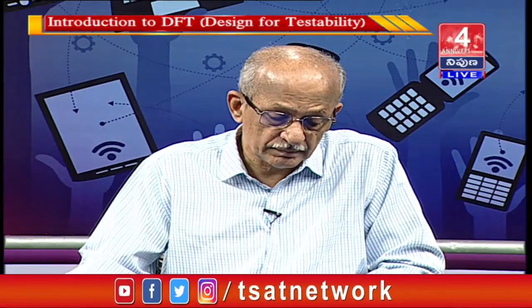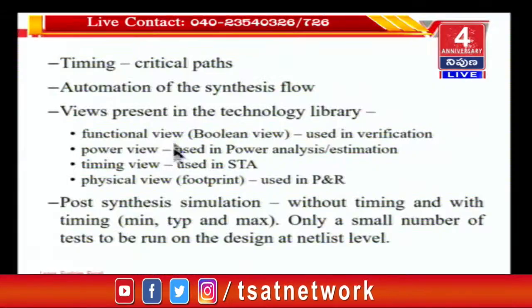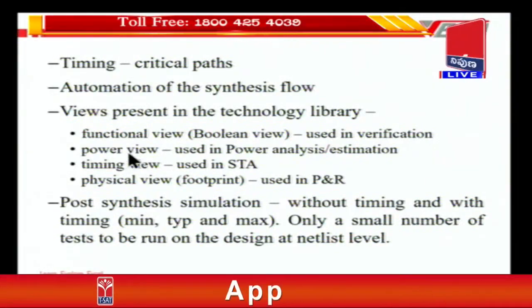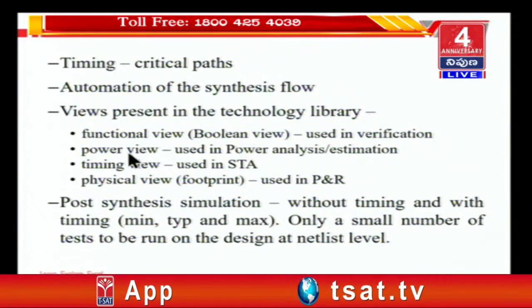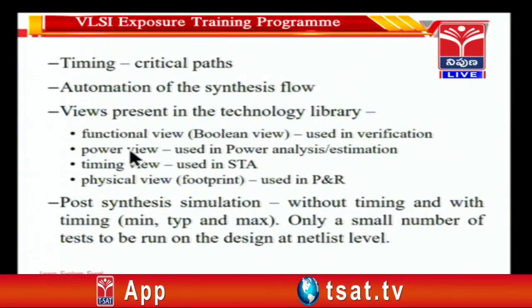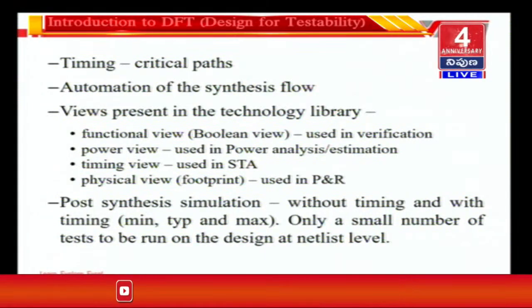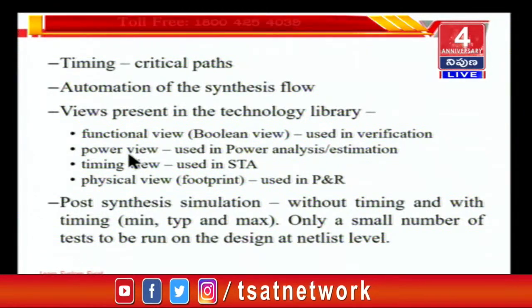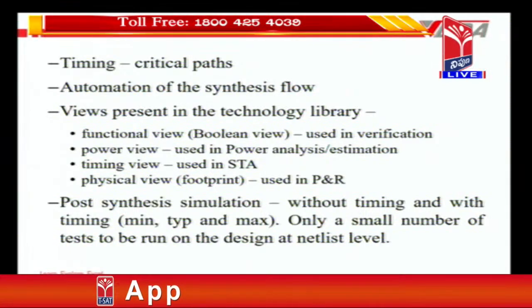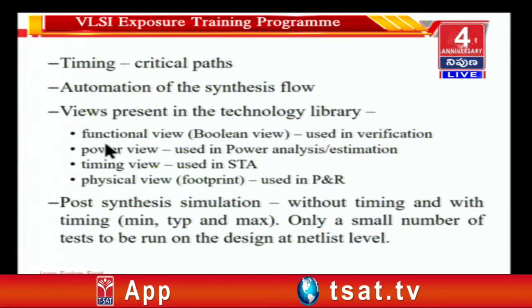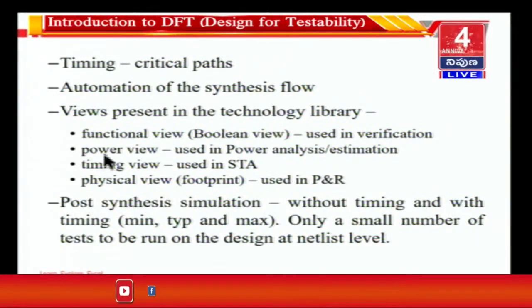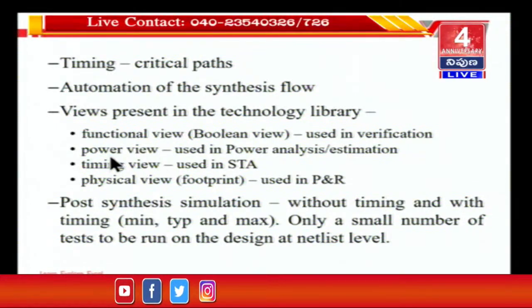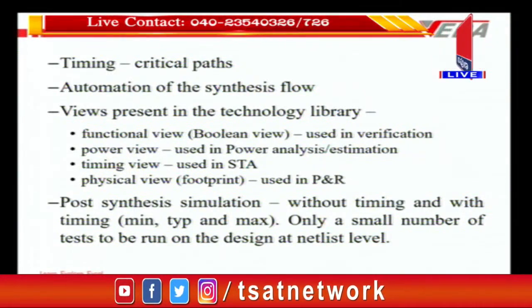As we have mentioned earlier, the power of logic elements in CMOS is directly proportional to the frequency, because frequency increases the switching activity in the circuit. Every time a circuit node switches from a 0 to a 1, there is some parasitic capacitance which is required to be charged, and this charging needs current. This current is drawn from the power supply. So every time a node switches from 0 to 1, power is consumed.